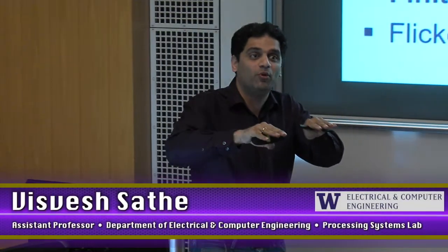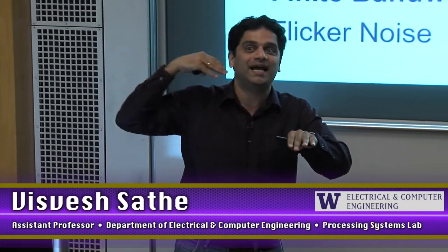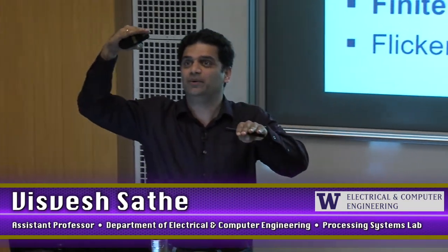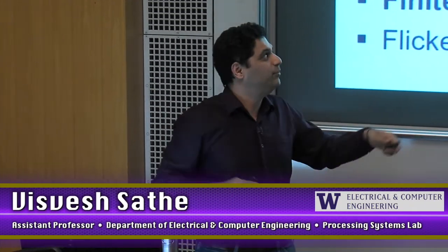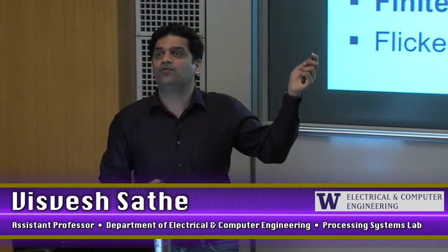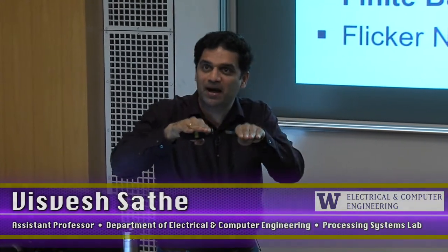A very simple, intuitive way to think about it is if I have a comparator and if I have finite bandwidth, I've evaluated a 1. When the clock goes low, I'm going to pre-charge both those nodes to 0. But I really need both those nodes to be pre-charged at the same value before the next evaluation. The one that had a history, having been evaluated to 1, is going to approach 0 but not really make it. And when you're talking about amplifying microvolts of noise, you really need those voltages to be bang equal.